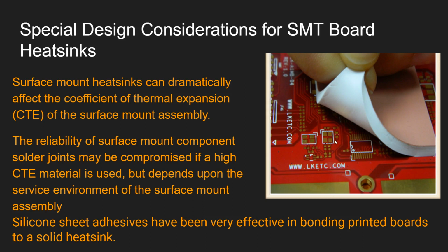In the design consideration, we have to keep in mind that vias under a heat sink should be avoided, as most adhesive systems use pressure during the cure cycle, which will allow the adhesive to flow away from the via, and this can generate a short between the via and the heat sink.